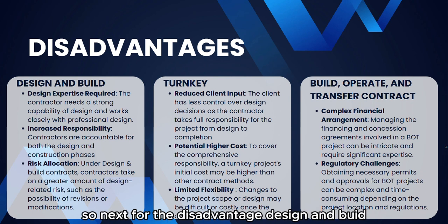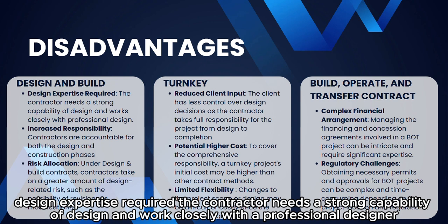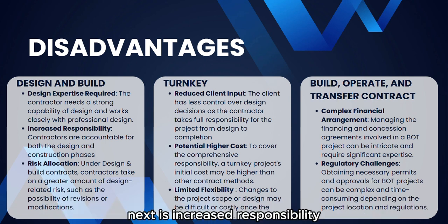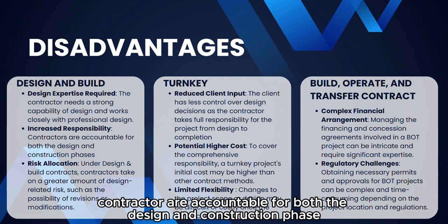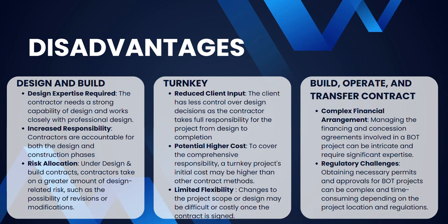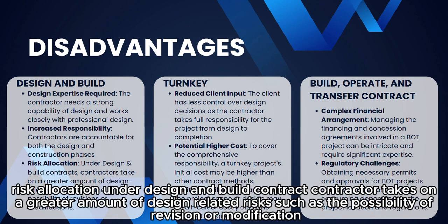So next for the disadvantage. Design and build. Design expertise required. The contractor needs a strong capability of design and work closely with a professional design. Next is increased responsibility. Contractors are accountable for both the design and construction phase. Risk allocation. Under design and build contract, contractor takes on a greater amount of design related risks, such as the possibility of revision or modification.